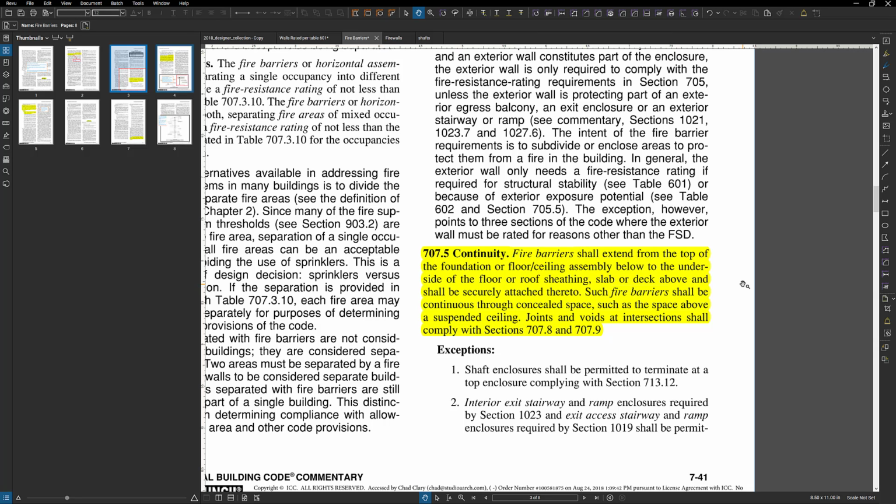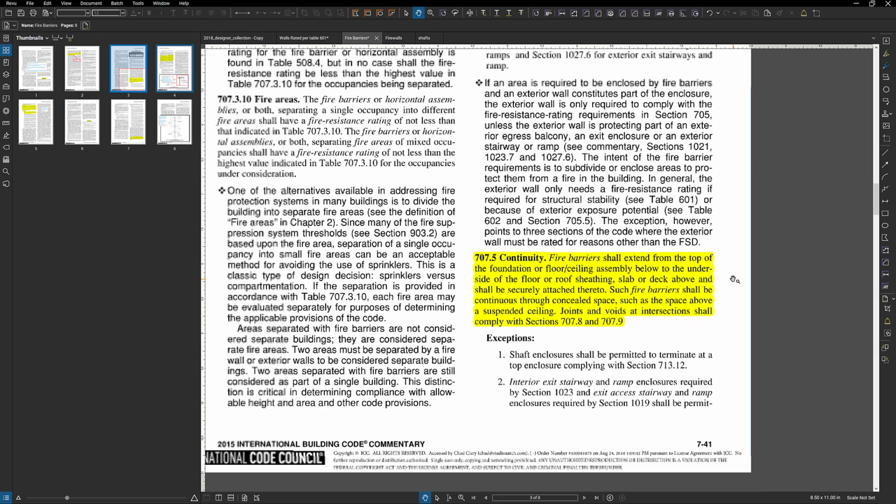They have special exceptions within the building code for stairs. For example, you'd say, I have a 2-hour stair wall that needs to have fire barriers. Well, those fire barriers continue all the way up to the underside of truss bearing for my roof. So they basically can have a 2-hour cap.